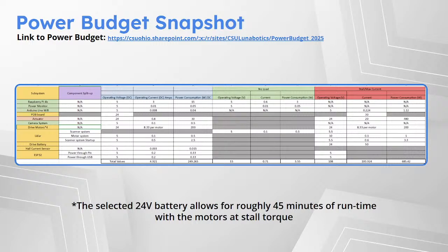Jared, I think it's somewhere in the 4 Newton meter range. 4 or 5 Newton meters. Yeah. The motors themselves, I think, only output like 2-point-something Newton meters, but then we have pretty beefy gearboxes on them that'll gear that down. The motors are good up to 1500 RPM, which is way more than what we need. That's way too fast if we were going to direct drive it. So we can get a fair bit of torque out of it with the gear ratio that we've got.